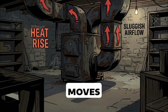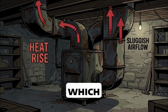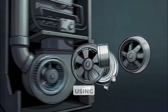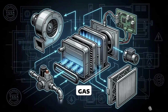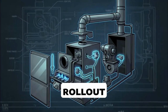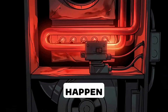Now, furnaces. A furnace heats air and moves it through ductwork. Older systems include gravity furnaces, which use natural air movement with no blower. Floor furnaces are installed in the floor. Modern systems are usually forced air furnaces using a blower motor. Main furnace parts include burners, gas valve, heat exchanger, blower motor, filter, thermostat, limit switch, pressure switch, rollout switch, and venting system. If the blower fails, overheating can happen quickly.